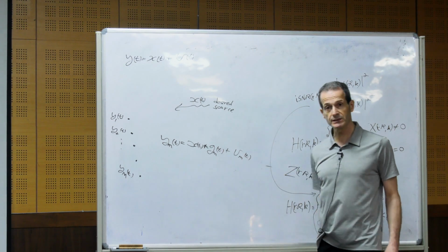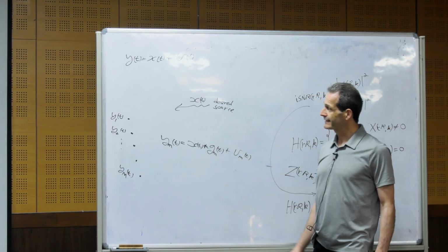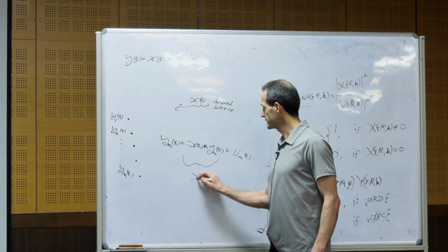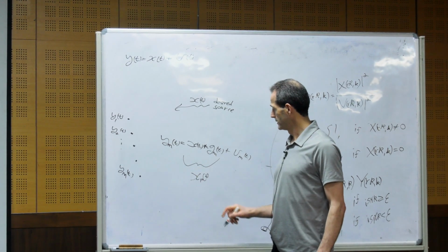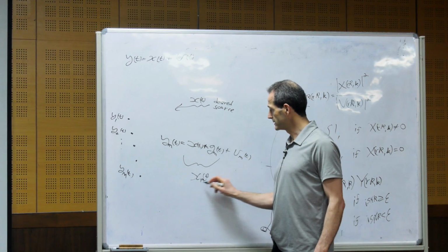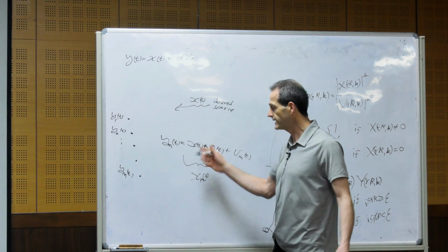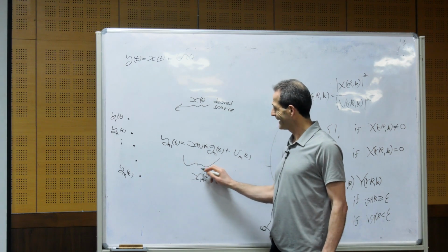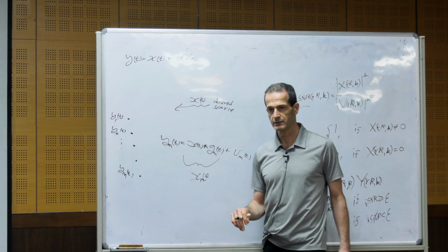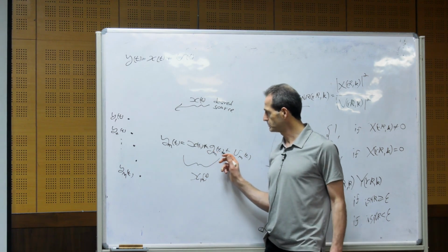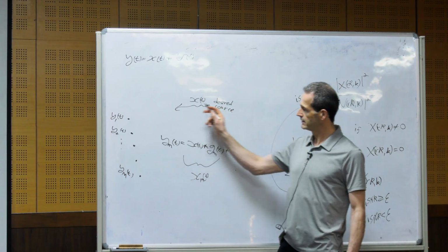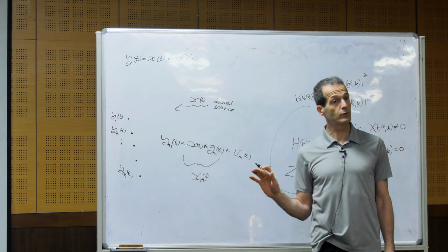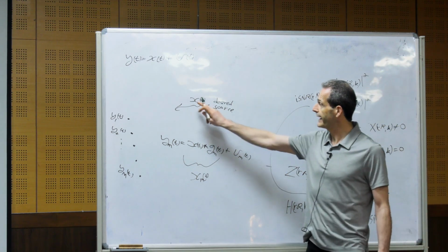If we know these impulse responses, it means that if we estimate x_m(t), the desired part of the signal that is received in sensor number m, then once we estimate any one of them, maybe x_1(t), and we know the impulse response from the source to that sensor, we can try to deconvolve and find x(t).